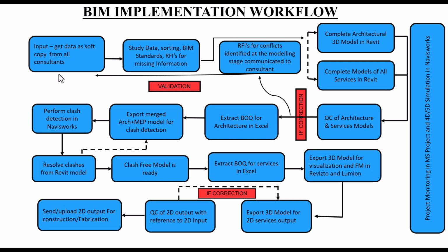You try to find out the necessary information about the families which you will have to create, and then accordingly you download the families or you make a family, you define which LOD you're going to create the model in, and so on, and then you proceed with the actual model.